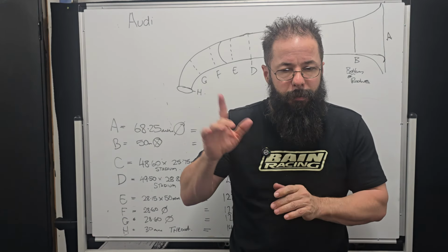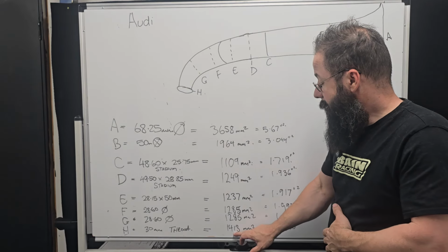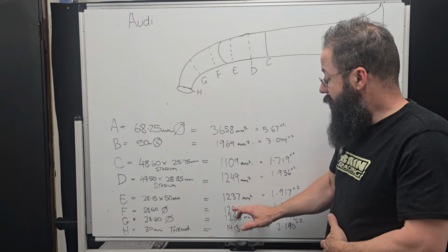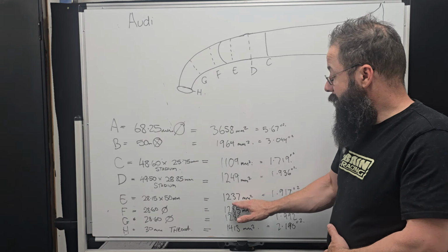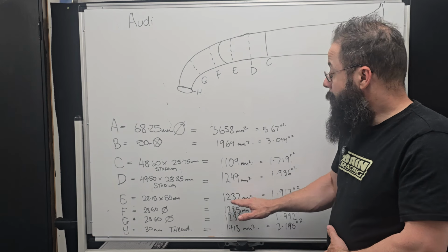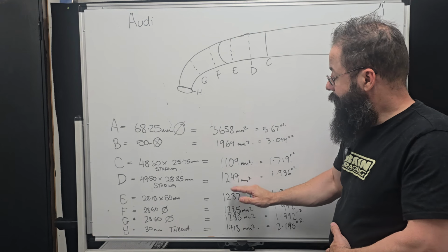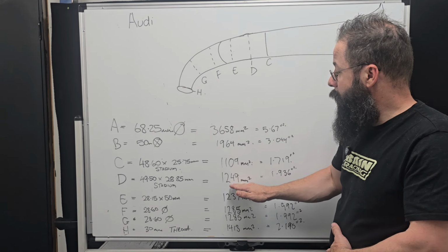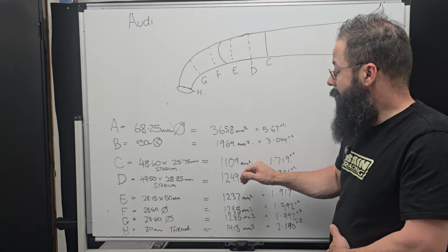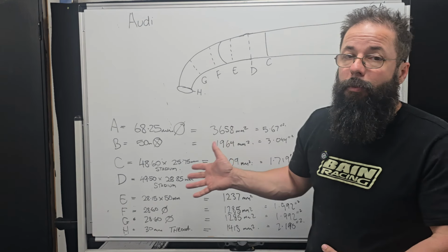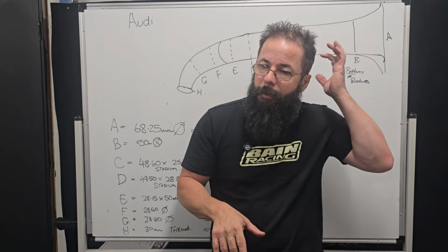If you compare those figures that we put in the Einstein app to the 2J, they were absolutely horrible. But as you can see, our throat and bowl area and blend up to the divider is where we're going to really look at. It could do with a little bit more in the E area, the body of the port, but we'll have a look at that. And the window is pretty good. So if we could lift this figure up to the window figure and then have the taper, it'd be pretty good, but there's not enough material in it from what I've seen already. So I'll look a little bit closer. We'll see what we come up with.